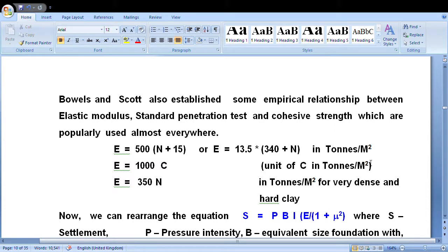My humble suggestion to you: besides calculating the elastic modulus from the laboratory compression test, we should cross-check it with the field values also, because some error or other influencing factors may be expected due to pressure increment in the laboratory compression test and preparation of soil samples.